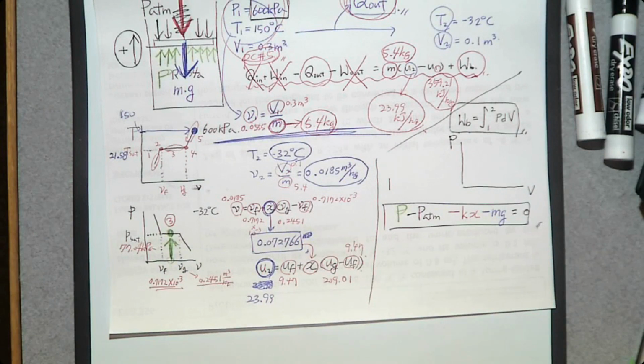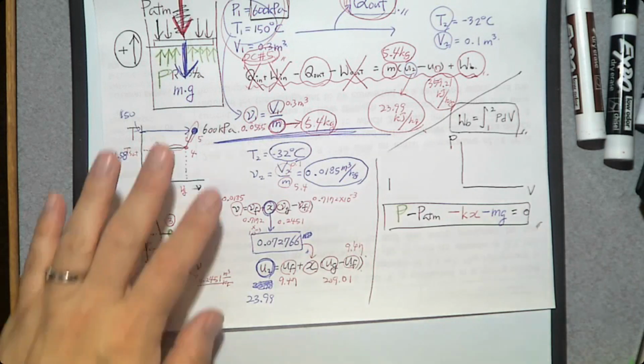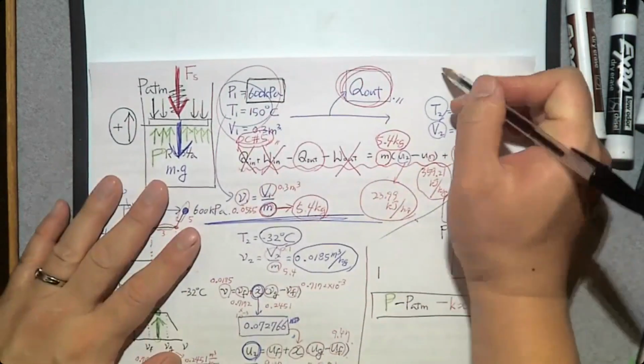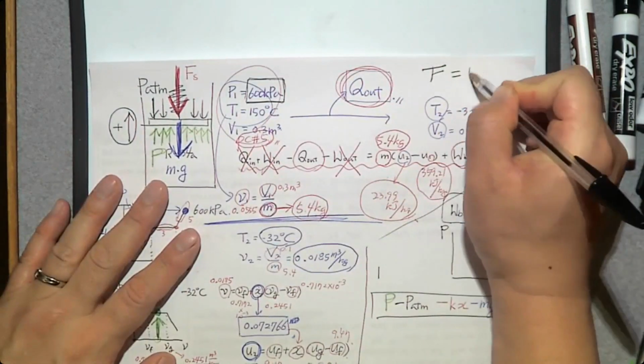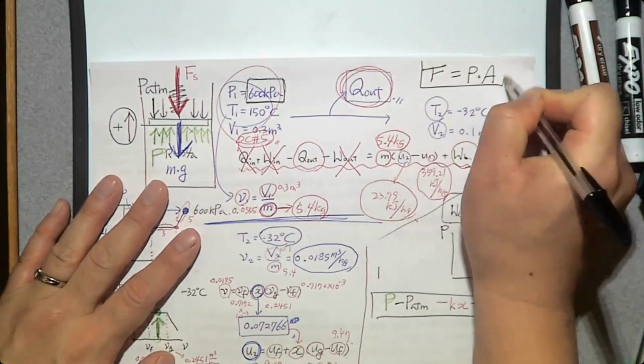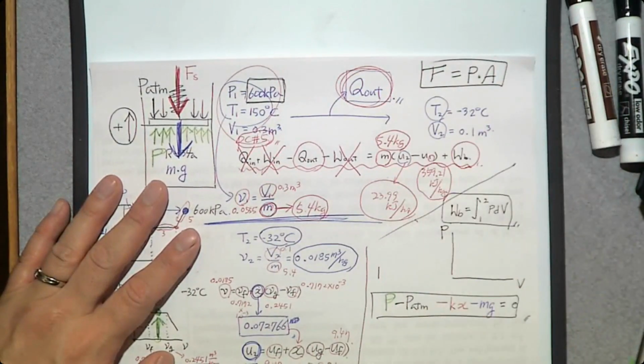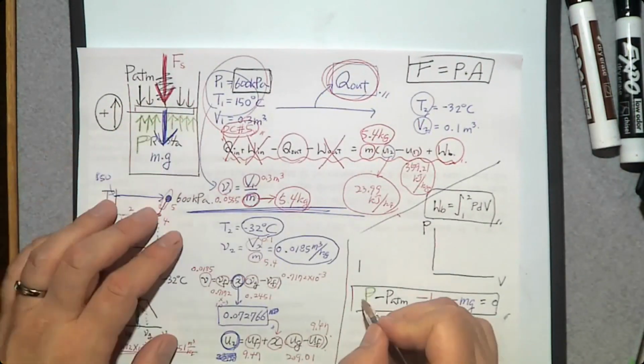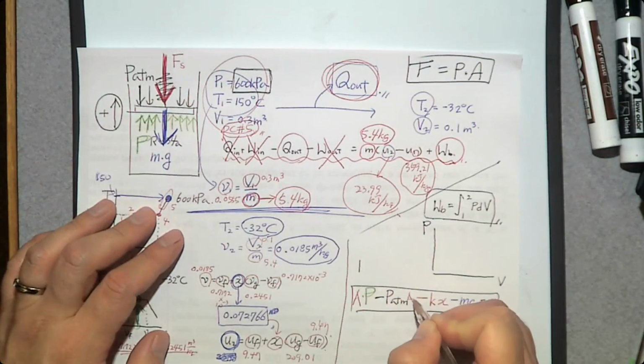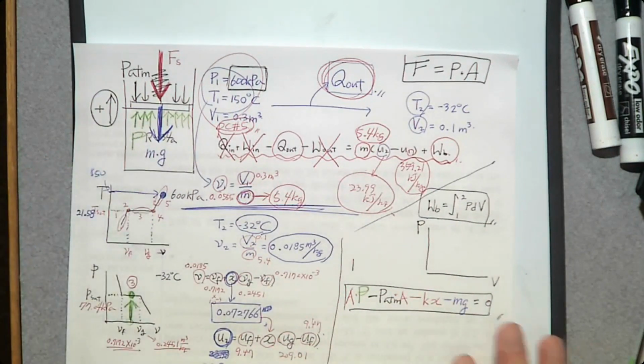Right, right. So this one is pressure. What is the unit? Pascal. This one is force. What is the unit? Newton. Pascal, Newton? No, you need to stick to one. So it's a force analysis. You can convert Pascal into force. How will you do that? F is pressure times area. So you need to multiply by the cross-sectional area of the piston. Then this one is correct.